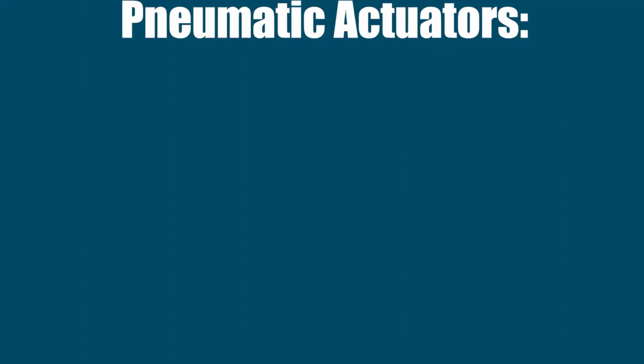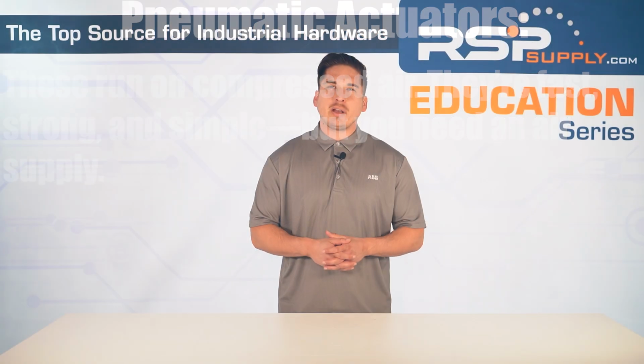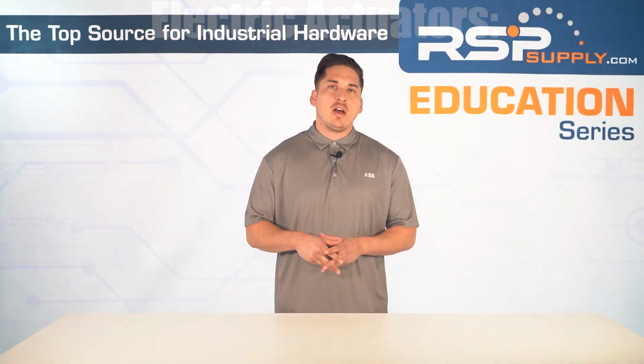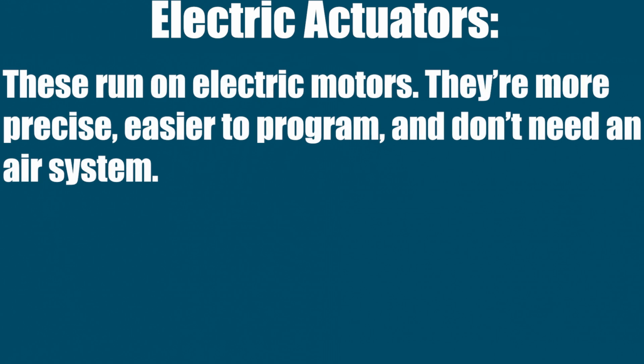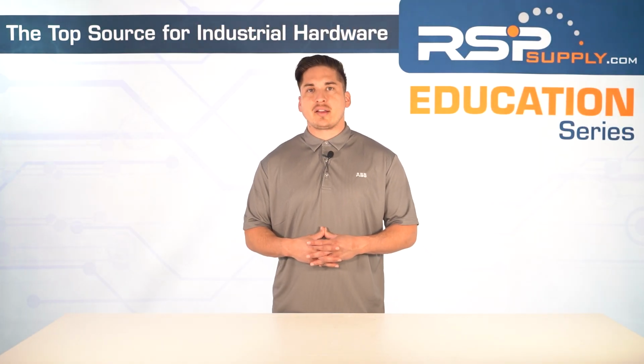Now let's talk pneumatic versus electric actuators. Pneumatic actuators run on compressed air. They're fast, they're strong and simple, but you do need an air supply. They're very common in oil and gas applications. Electric actuators run on electric motors. They're more precise, they're easier to program, and you don't need an air system. You'll often see these in water treatment and HVAC systems.